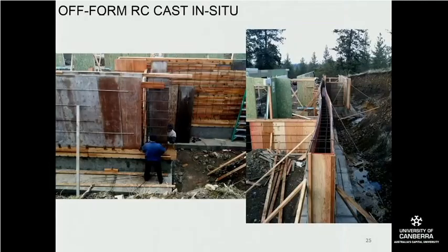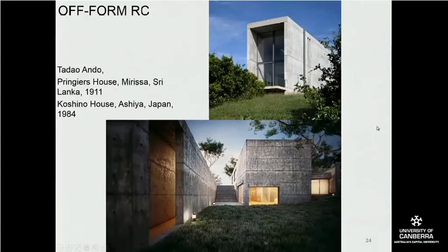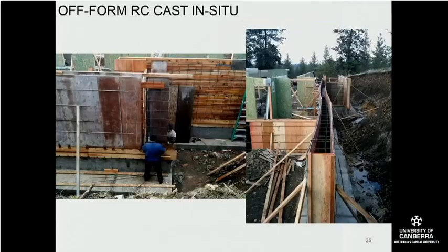So this form of construction is mostly used nowadays for retaining walls, as you can see here. Although Ando actually likes to use monolithic concrete, it's too expensive in most cases as a construction method, and people save its really high strength for retaining things. So after this is poured and sets, the back will be waterproofed, and then they will backfill with earth. So this will become part of the hill back there.